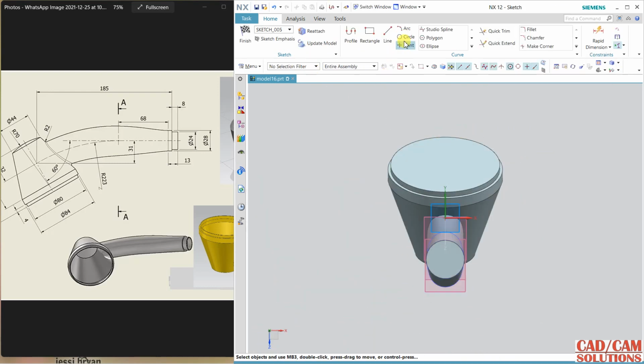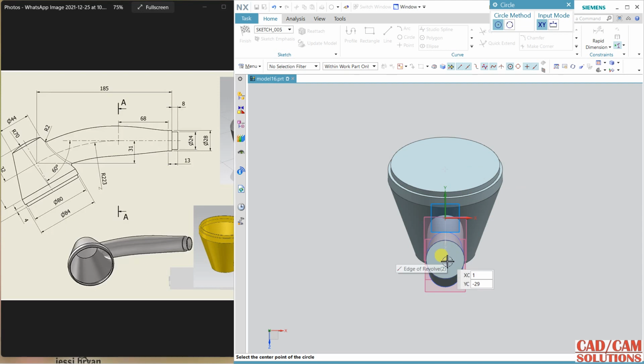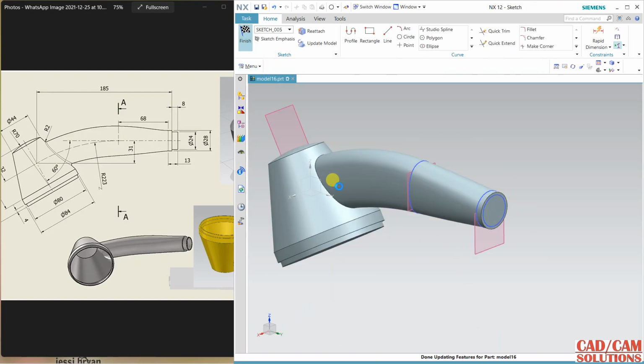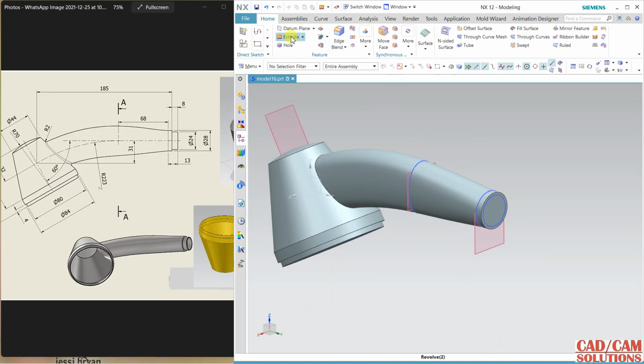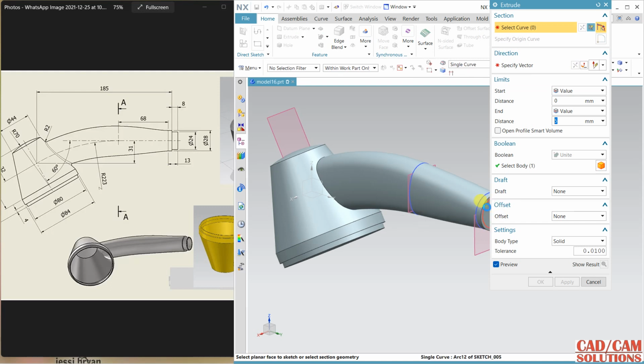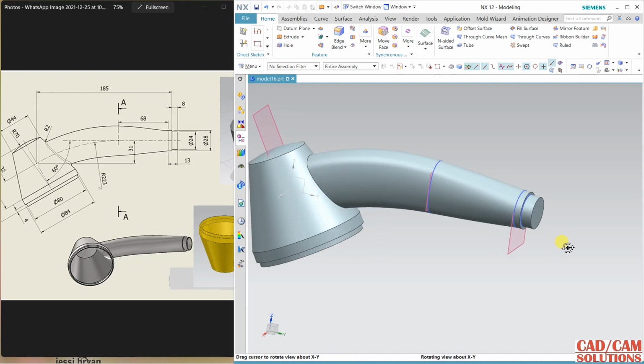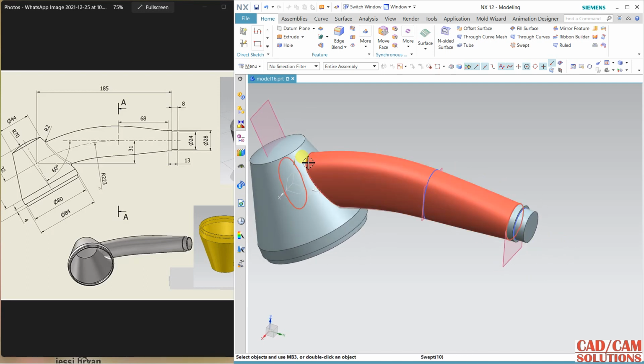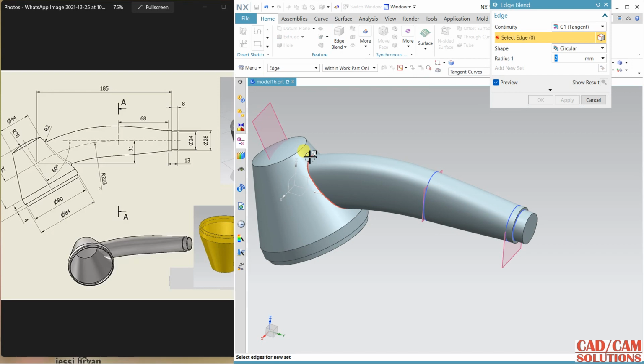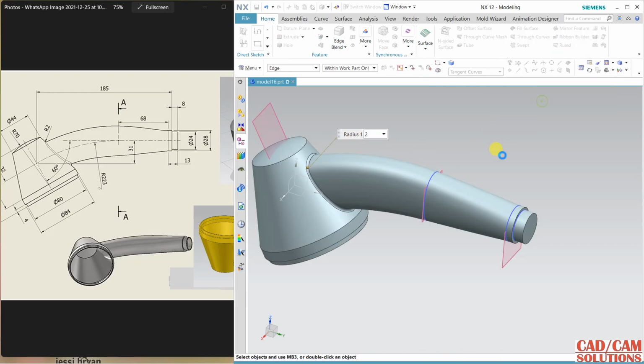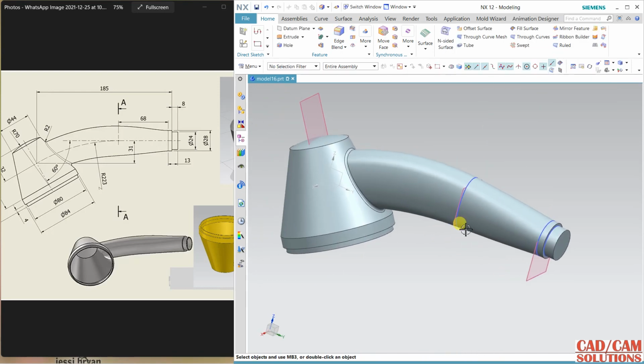and the next circle is 24 in diameter, 24 diameter, finish and extrude it 8, so extrude this circle 8 mm and unite. Okay, we have to define one plate here, and the plate is 2 mm, so click and okay. Now hide all the planes and sketches,